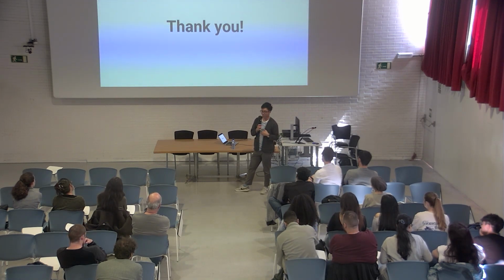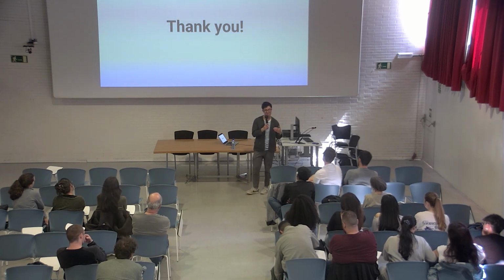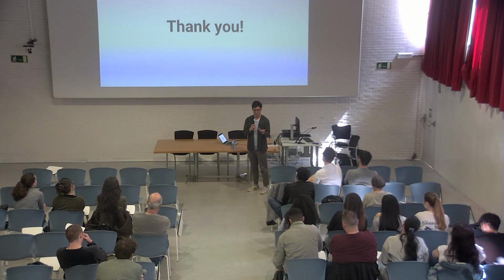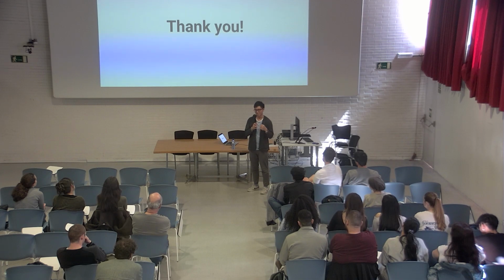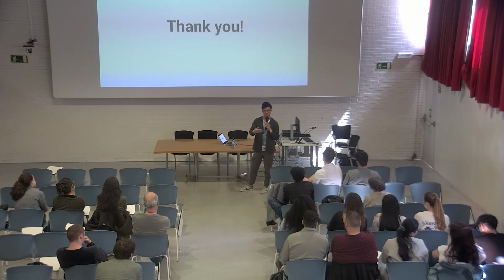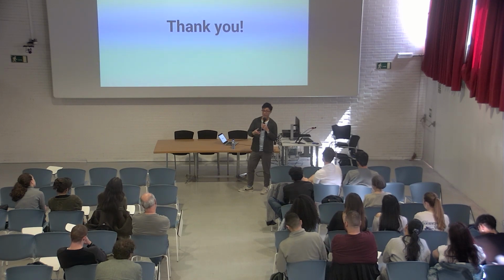One of the disadvantages that Karamba has brought is that people who don't have an understanding of structures put their structure into Karamba. They might have actually modeled it incorrectly. Karamba might show a result that shows it's working, and then you might just assume that your structure is already working, right? But it's not such a linear process. This is the challenge of really using Karamba in your projects: it's not just about getting a utilization below 100%, but also checking to make sure that your structure is actually performing as you intended it to.